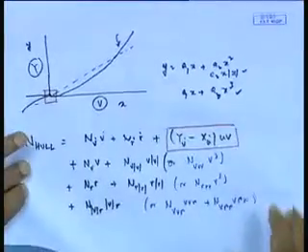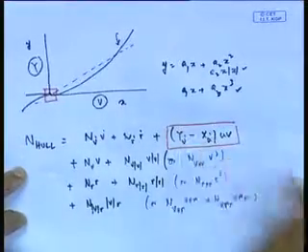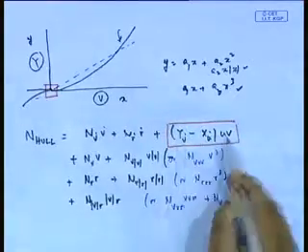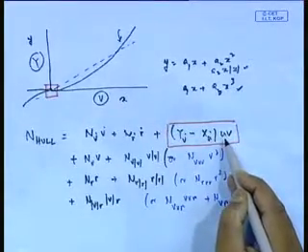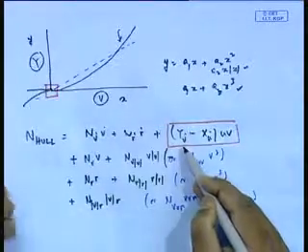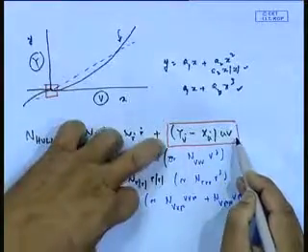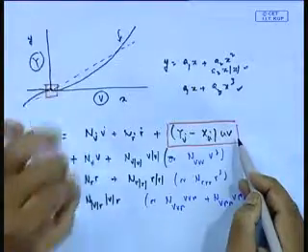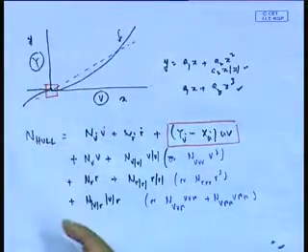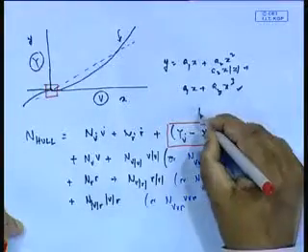But here the problem is that this particular term is always negative for a positive v, because Y v dot is a very large number. So, this value always represents a destabilizing moment, and this is known as the Munk moment. In fact, this is something that is very important in our marine objects.